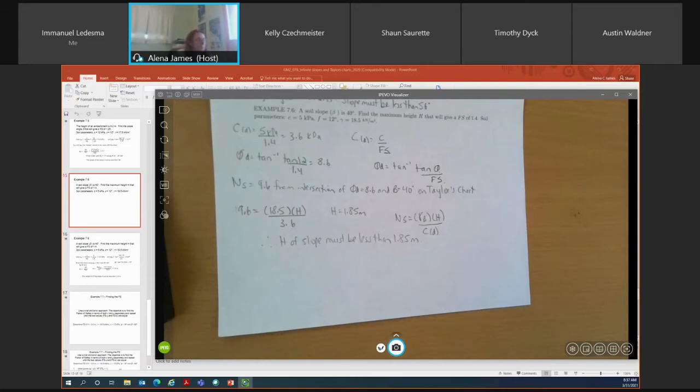Okay. So it doesn't really matter what soil it is, you're just going to assume it's 0? It has to be a clay soil for it to have a friction angle of 0. So it has to be a material that has cohesion. So it would be material that you tested through your unconfined compressive strength testing or triaxial testing. Okay.